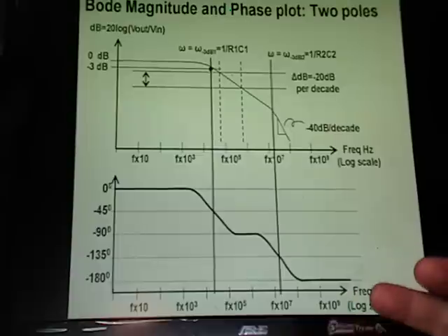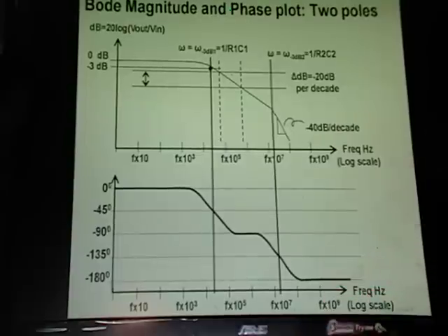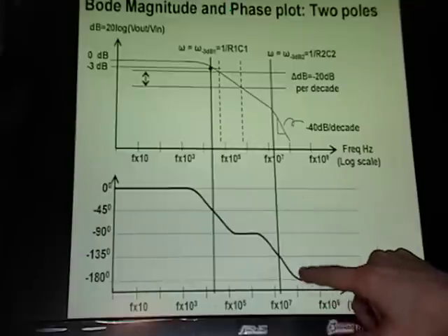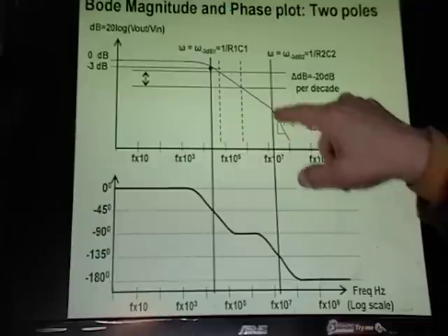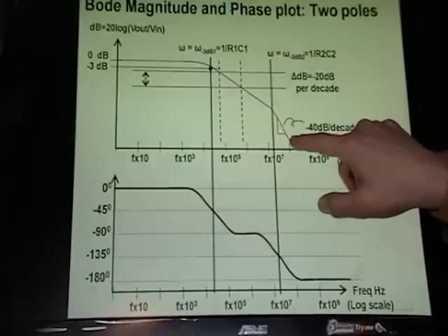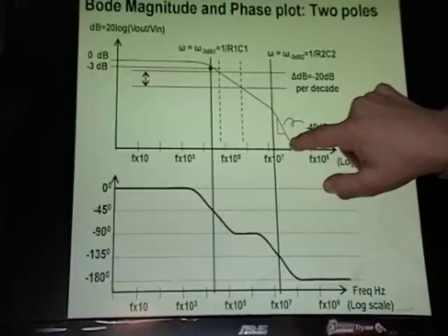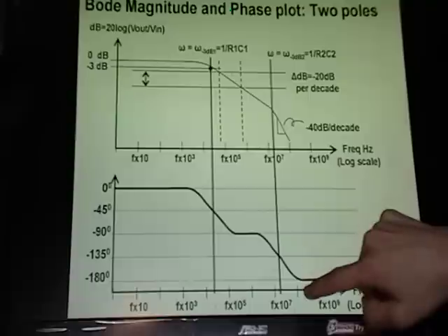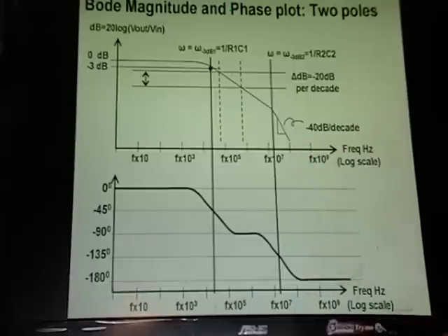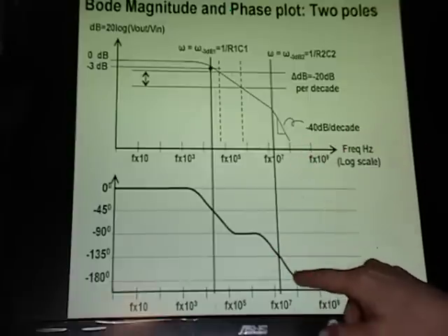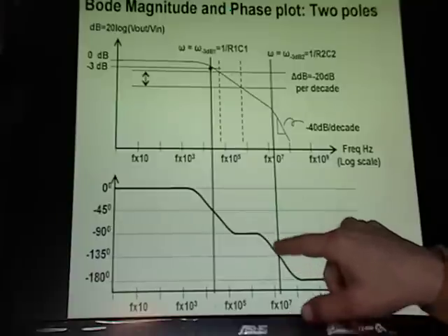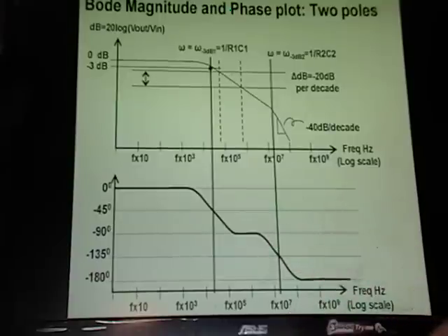If it doesn't have feedback, this doesn't matter. But if it has feedback at 180 degrees plus or minus, and the amplitude of the output of your amplifier, or the gain, is greater than 1, in other words greater than 0 dB, then your circuit can be unstable. And in general, you don't like to be at 180. You like to be back, 30, 60, 45 degrees here, and then you don't get such a big effect from that positive feedback.